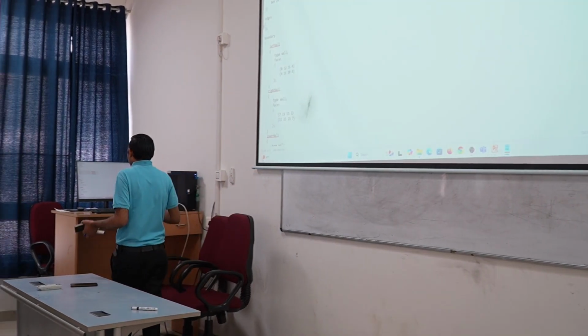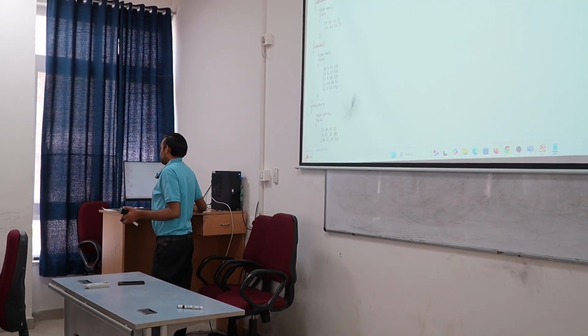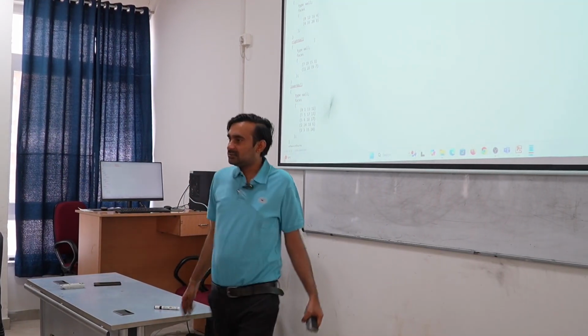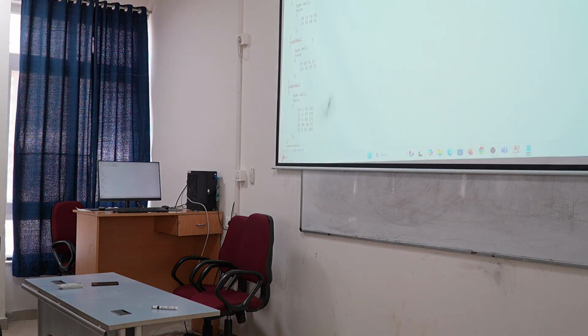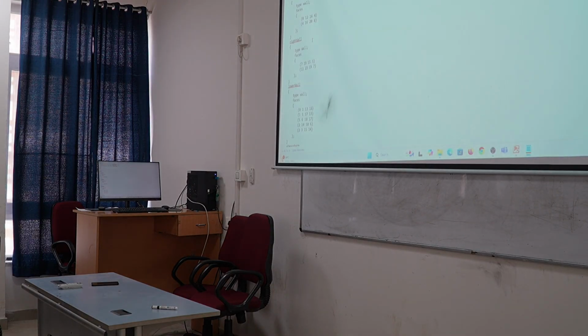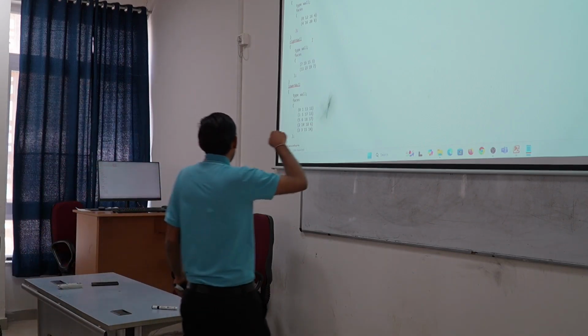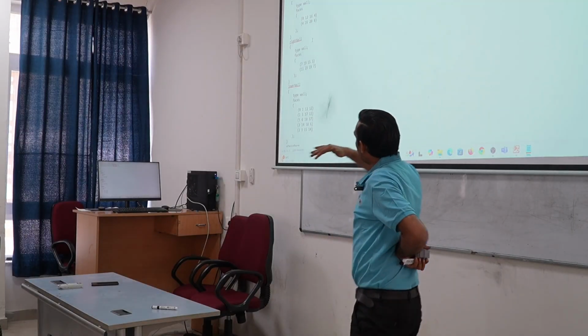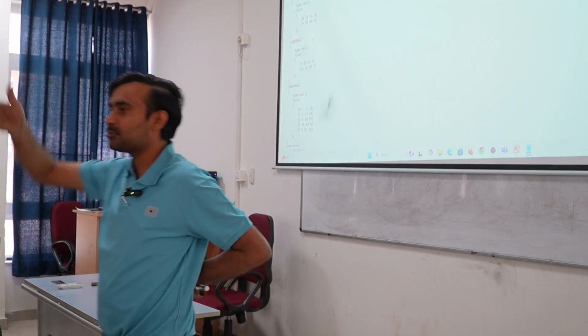After this I have one important point, that is boundary, because later on in my simulation, I need to tell that at different portions of the geometry, what are the boundary conditions. So, to define the boundary conditions, I must specify in the mesh or geometry itself what faces will be subjected to what type of boundary condition. For that purpose, we are using this boundary type, and within it I will be giving names to different boundaries.